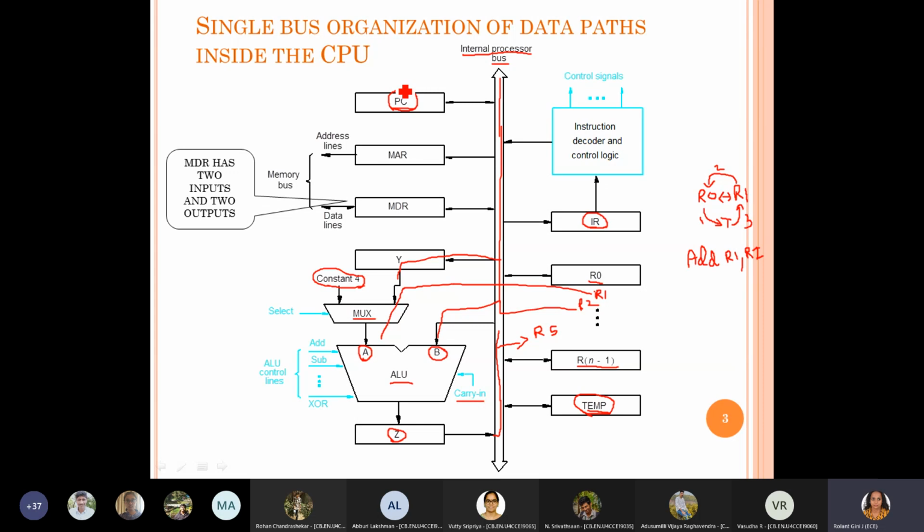So the program counter value will be added with 4, and the incremented result through Z is again stored in the program counter. We are doing an increment by 4 here, assuming that it's byte addressable memory and each instruction is 32-bit. Based on those things only we give the constant 4. If it is a Thumb instruction, you know that it's only 16 bits. In that case, this increment need not be 4. Either you can increment by 2 and take each instruction, or increment by 4, read the whole 32 bits, which in case of Thumb gives you 2 instructions, execute the first 16-bit instruction, and then take the next 16-bit instruction and execute it. That way also you can do the operation.